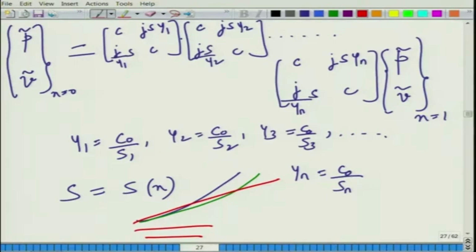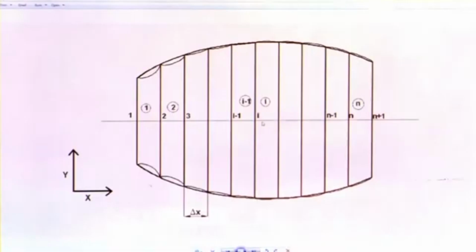So, as a stepping stone to the main CCTR problem, we will be considering again the gradually varying area duct problem without any perforates, using the matricant approach, where the ducts are modeled as notional segments, but with small segments of exponential profile. So, this is approximately a short exponential profile, such that the discontinuity is not there, and for an exponential profile we know the transfer matrix. So, then it is just a matter of gradually multiplying the transfer matrices and getting the solution. So, we could do that and analyze a CCTR using a matricant approach also.